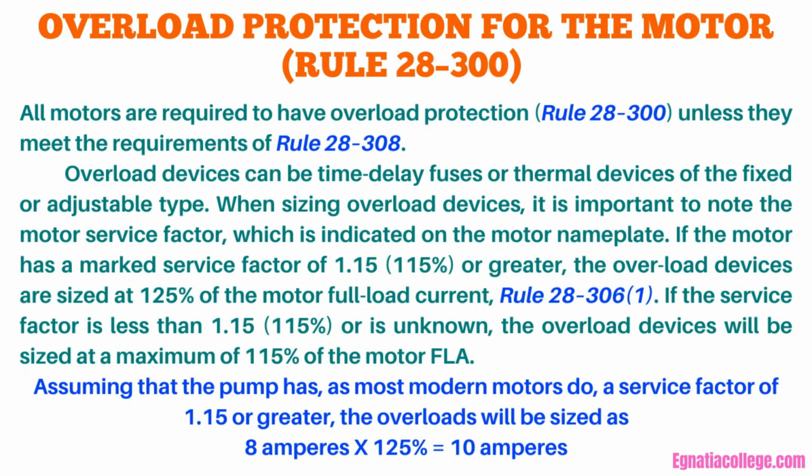Overload protection for the motor, Rule 28-300. All motors are required to have overload protection, Rule 28-300, unless they meet the requirements of Rule 28-308. Overload devices can be time delay fuses or thermal devices of the fixed or adjustable type. When sizing overload devices, it is important to note the motor service factor, which is indicated on the motor nameplate.